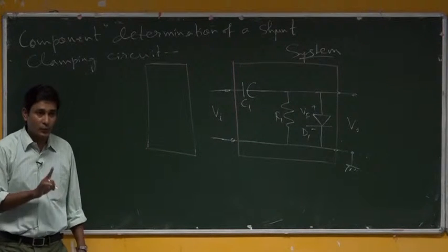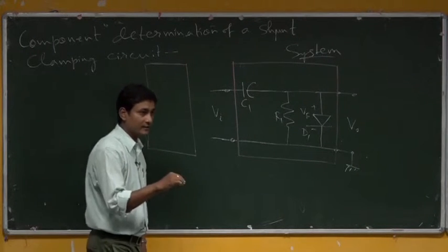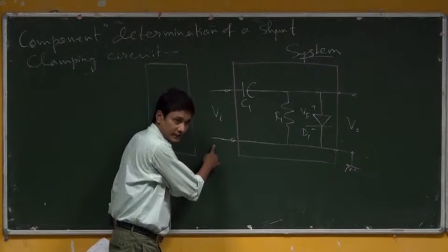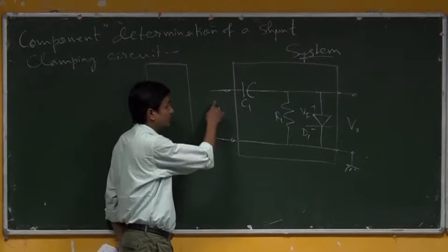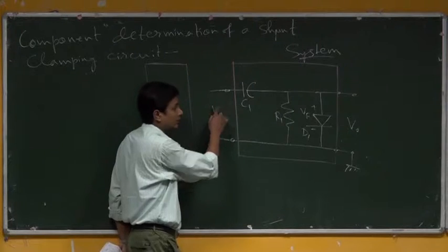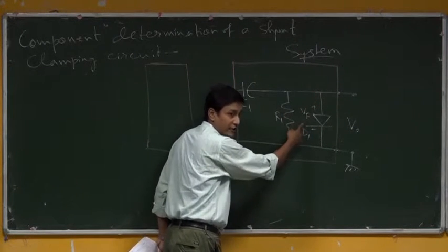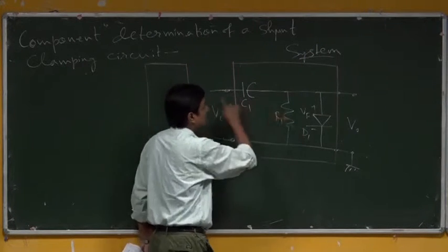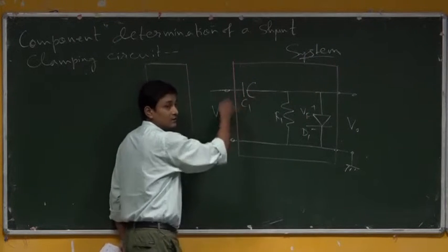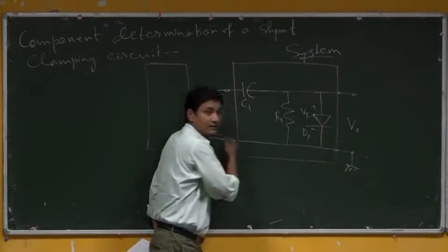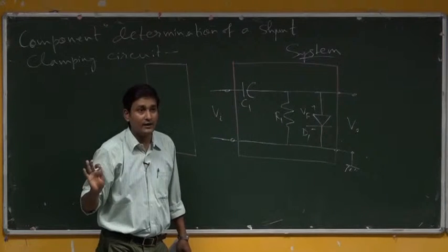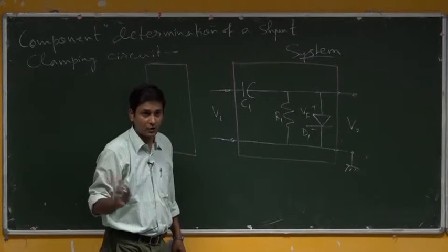This is an individual system which we have discussed already. What happened in this, quickly, if I recollect? We applied a voltage here, and initially for the positive voltage it made this diode forward biased. So, the voltage across this became Vf, and it happened immediately because C1 through the diode faced no resistive path. So, it was charging quickly.